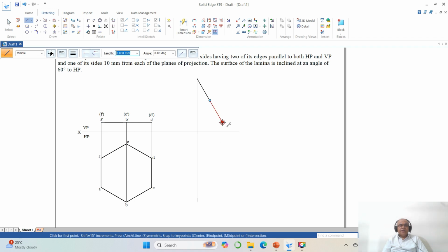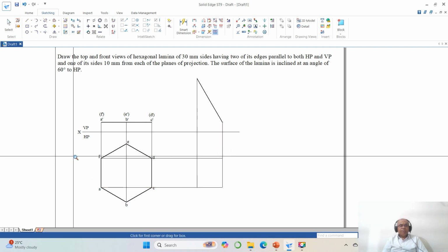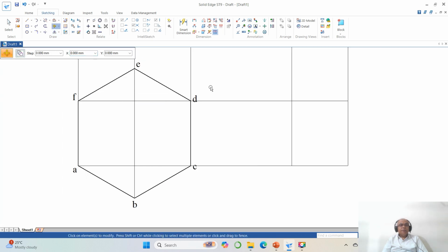Similarly, from here, you take endpoint and draw a vertical line. And then from these two, horizontal. Okay. Similarly, from A and C. Okay. Then go to trim corner between these two and between these two. Similarly, between these two. Okay. Once you do that, now you go to zoom window, go to move, disable copy, you select this and keep it out. Okay. Then go to fit.